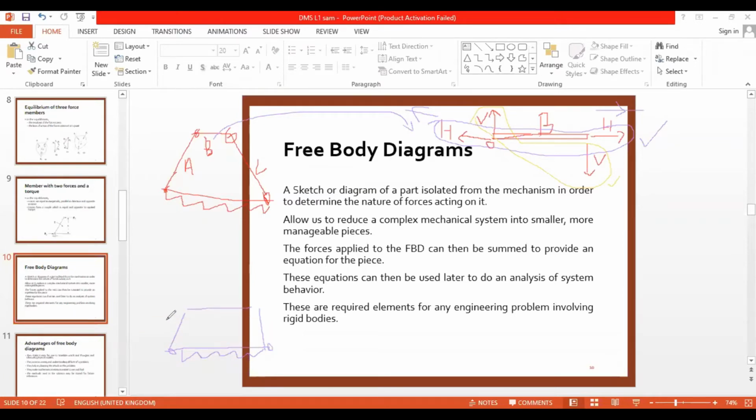At each point, if there is any relative resultant force, then this link will not stay like this, because if there is a force, either it should move or it should break or something. Since nothing is happening, I will assume this F is 0. I told you, while breaking each joint, we will have a vertical as well as a horizontal component.